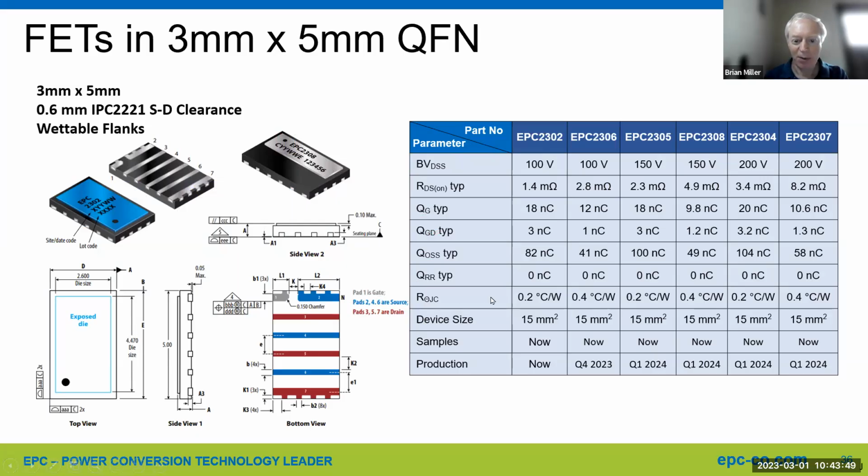It's not shown here, but there is a good conduction from the junction to the board. Not as good as this, but it is pretty good. So it depends on your design. To maximize the thermal performance, yes, top cooled is the best. In some cases, if you can cool through the board or in-pad vias, then you might be able to have no heat sink and do adequate cooling in a bottom cooled situation.